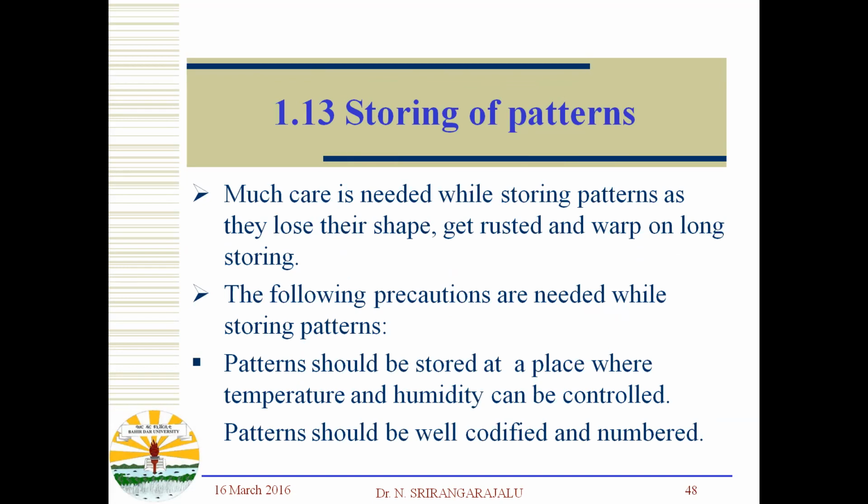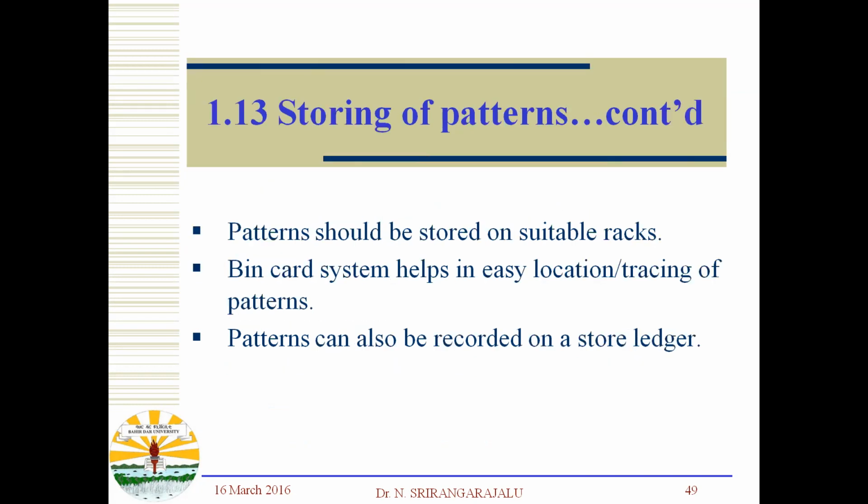So much care is needed while storing the patterns, as they lose their shape, get rusted and warped on long storage. The following precautions are needed while storing patterns. Patterns should be stored at a place where temperature and humidity can be controlled. Patterns should be well confined and numbered. Patterns should be stored on suitable racks. A bin card system helps in easy location tracing of patterns. Patterns can also be recorded in a store ledger.